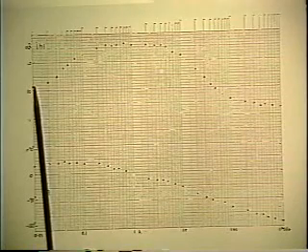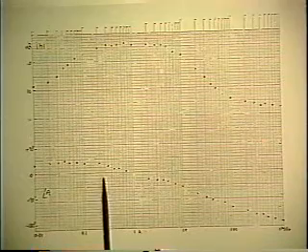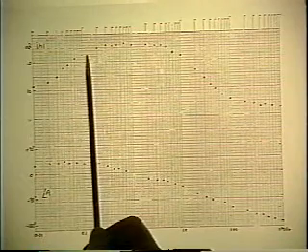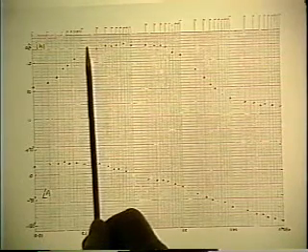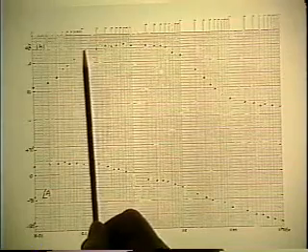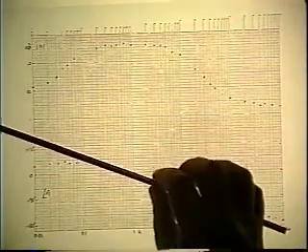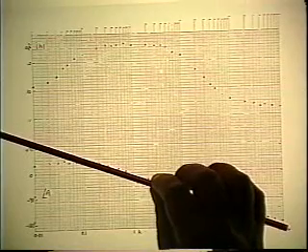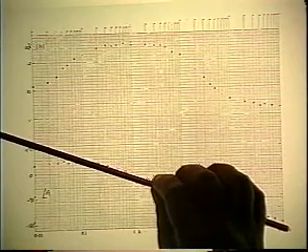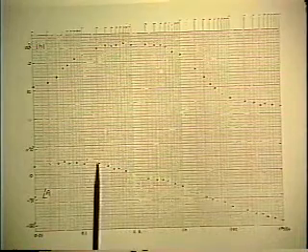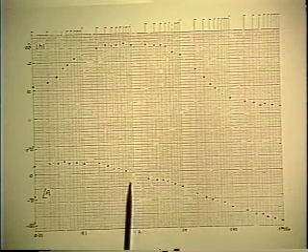Okay, the first thing to do is to check that the phase data we have is consistent with the pole that we've already identified from the first intersection. So if there's a pole there, there must be a minus 45 per decade phase asymptote to go with it. And when you draw that, you find that it fits these data points pretty well down here.